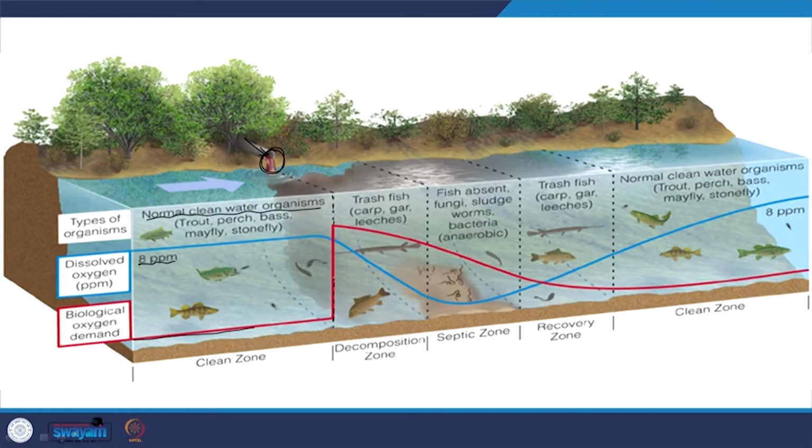So, the organic content in the mixture of the river and the wastewater takes a huge jump. DO does not fall immediately, it will decrease but will not fall immediately. But now the DO is going to start decreasing. Why is that? Because the microbes are going to degrade this organic content in the presence of oxygen. So, the organic content is going to decrease.